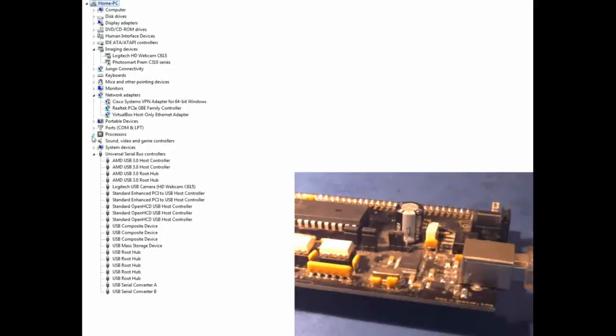Once the drivers reload, you should have a new entry in the device list called Ports (COM & LPT). Expand this entry. Under this entry you should see a USB serial port at a given COM address. Note this COM address as we'll need it later. We've now completed the hardware configuration for the board.